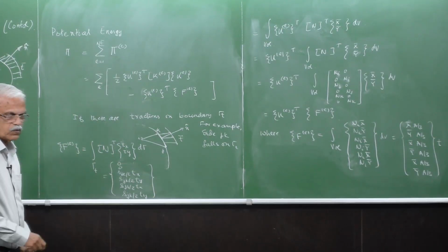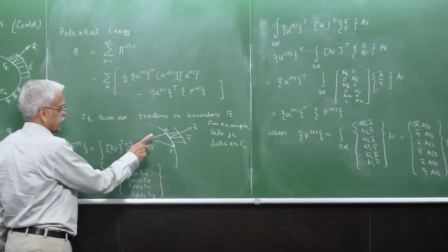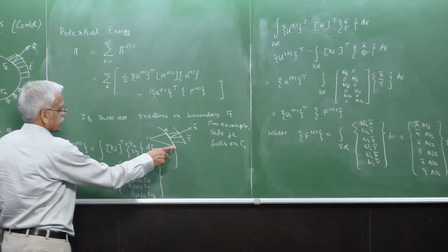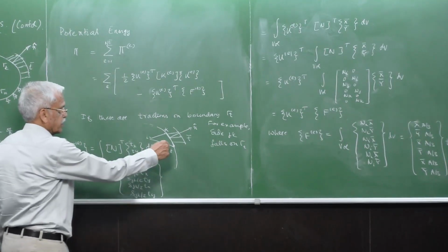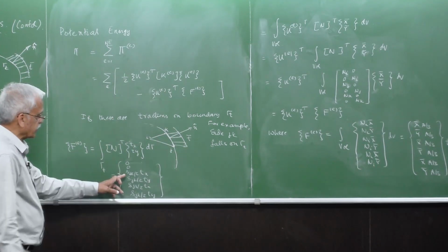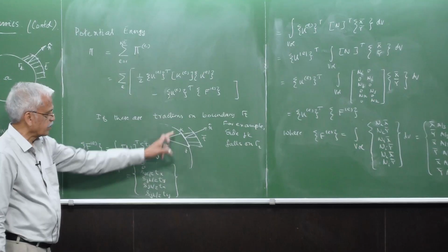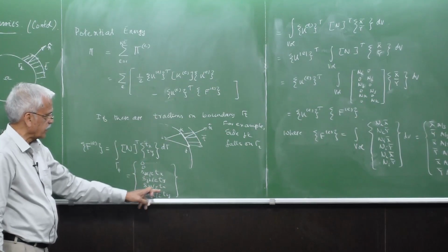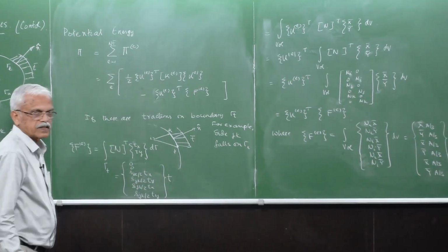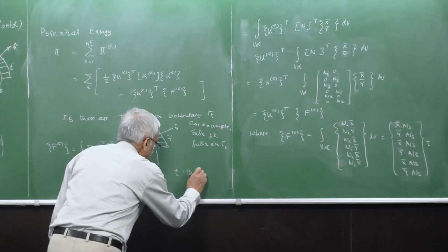okay. So the first two are due to the shape functions at node I in x and y directions, which turn out to be 0 on this side, and then J has a shape function here which is equal to 1 and goes to 0 at K. So that's why the integration gives SJK by 2 TX, SJK by 2 TY, that's the y component, and then SJK by 2 TX and SJK by 2 TY, and of course a multiplication by t, the thickness of the plate. This we are writing